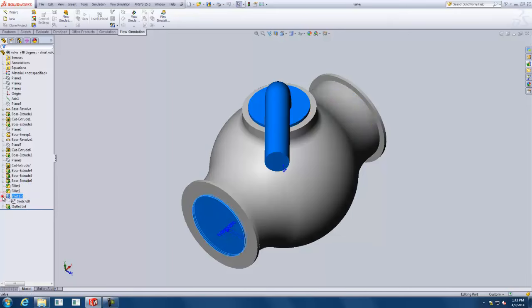If you note how these are made, these are done with a sketch, just a circle at that end and then extruded slightly. What we're going to do is use the lid feature in SolidWorks, which makes things really easy. All right.